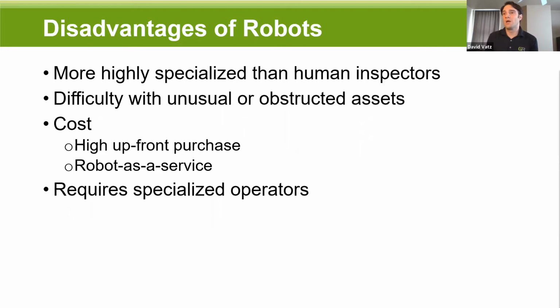Then there's reduced downtime, so you could shorten the length of an outage by getting robotic readings faster than manual inspection. And also more targeted inspection frequencies. Instead of inspecting something every year, maybe you inspect it every 2 or 3 years, but with higher density data, and that allows you to save money by having fewer inspections.